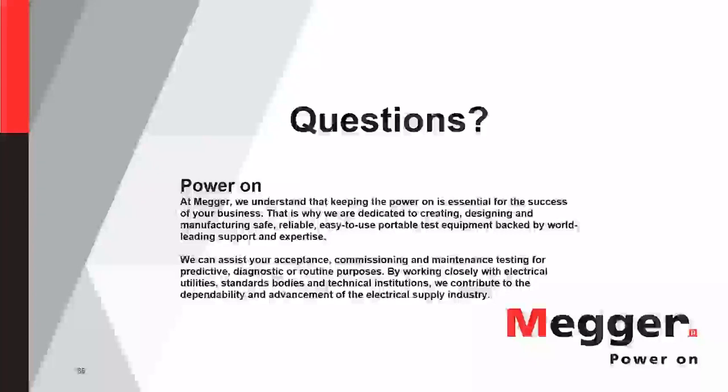If you're in the field use, once your transducer is calibrated once, if you're looking through and you're getting your good measurement and everything's going through, I generally don't calibrate that often, maybe every few years or so, 4 or 5 years, or if I just see a bad operation. Whenever I see bad results, I assume I did something wrong first, check all my connections, then I assume my equipment's wrong and verify that if I can, move a transducer around or swap it out. And then lastly, I start looking, hey, something is wrong with this circuit breaker, just to see. But as far as calibration goes for field use, once you verify that original calibration of the transducer, you're not doing it that often. I'd say 4 or 5 years would be fine.